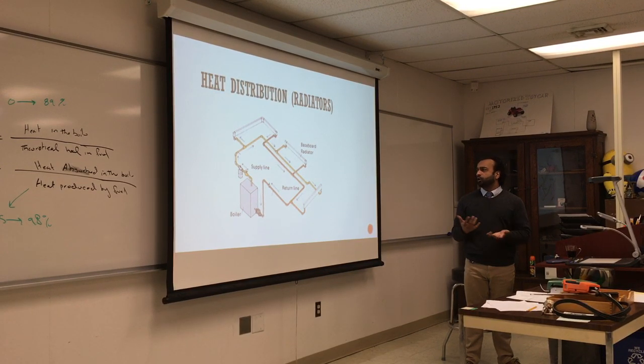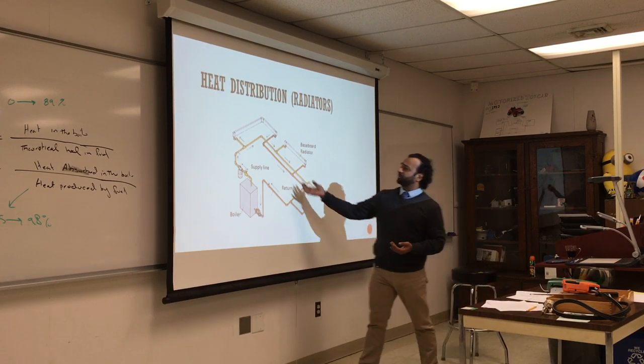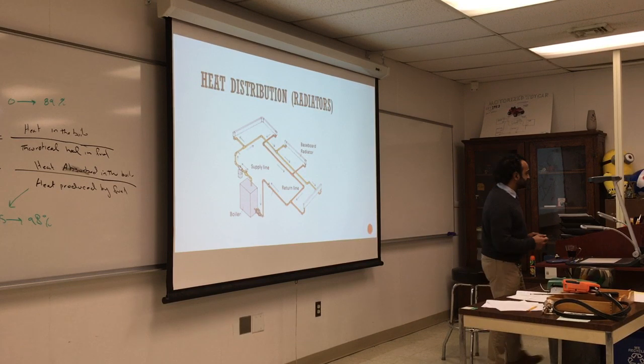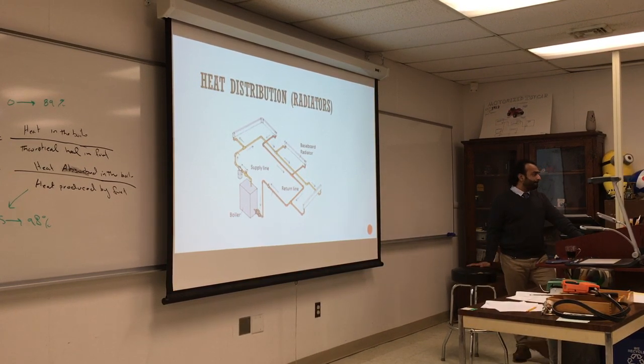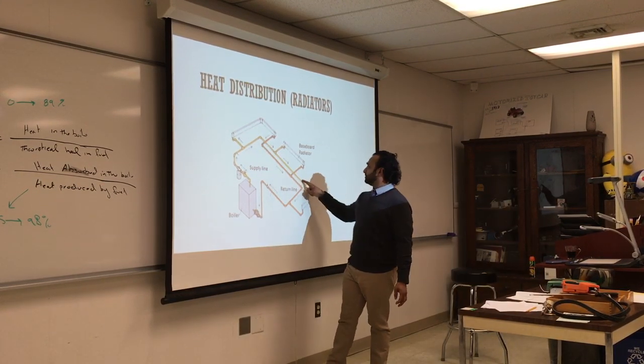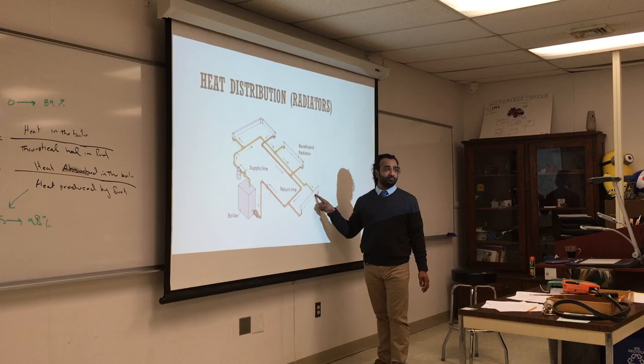I think at the end the output is going to be similar, but it's mostly about how to balance the temperature in each radiator, so one will not be as hot as the others. But like, you know how it goes to three different baseboards? The first one is obviously going to have more heat. No, if you notice, the temperature in the supply line is going to be the same, and the pressure is going to be the same.